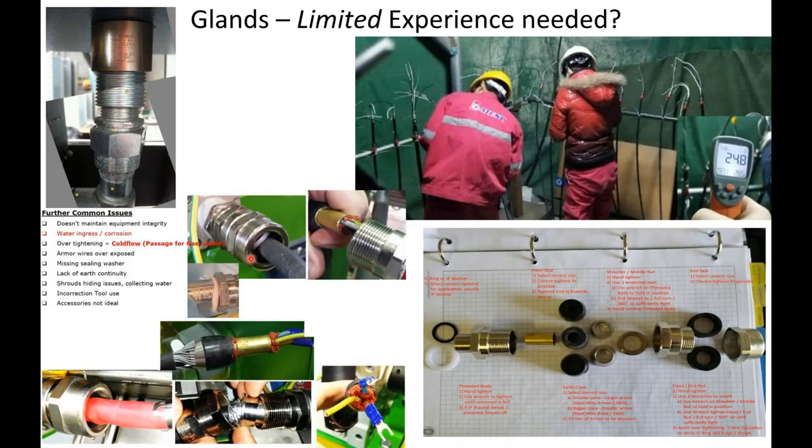Water can get in. People say that IP ratings have nothing to do with hazardous areas. I disagree. Creepage and clearance distances, making sure that arcing and sparking won't happen, is very important with each EX protection technique. When you get dust and water in there, any liquid, that causes a problem.